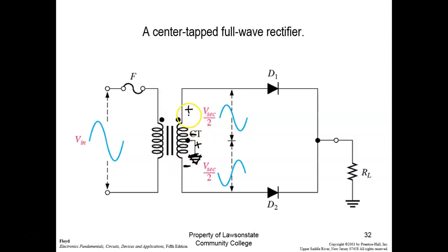Okay. So what happens if this is a 12.6 volt transformer? This guy right here's got 6.3 volts. So it's like a resistor. If I have plus 6.3 volts there, what would I have right here? Well, it's going to be minus. I would have 0 in respect to that, right? Does that make sense? Now, if I come down through here, this guy's got 6.3 volts.